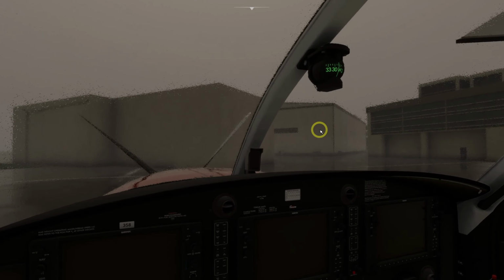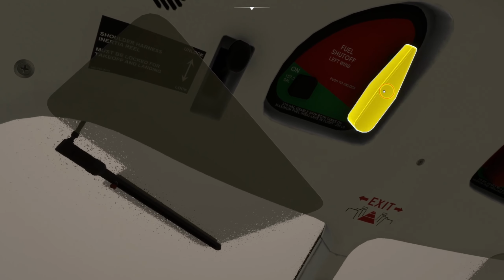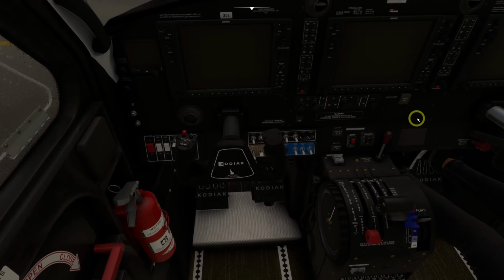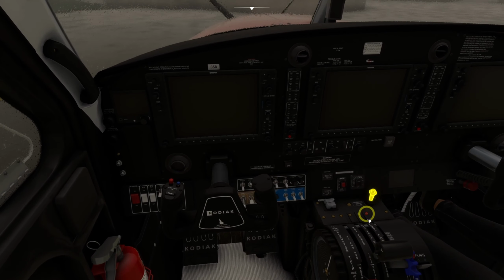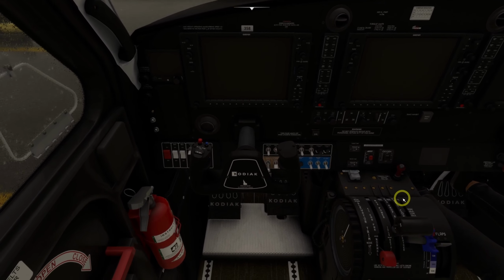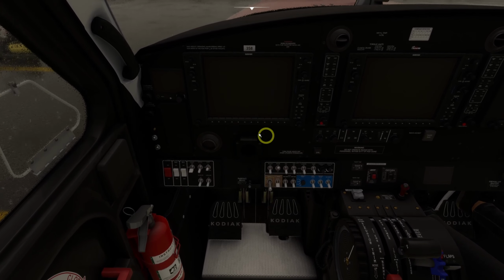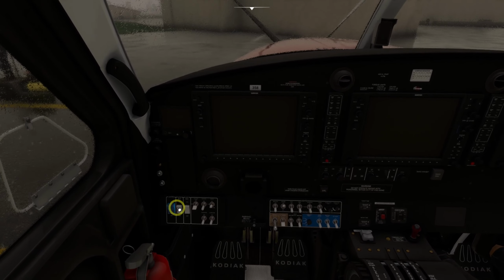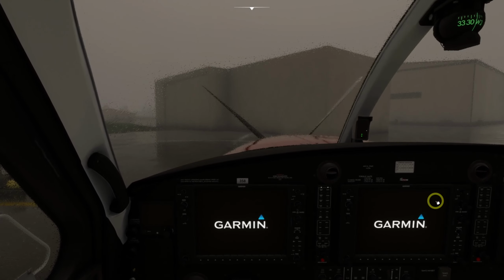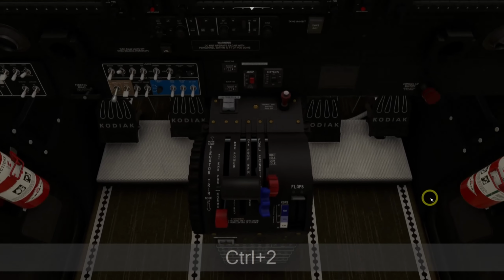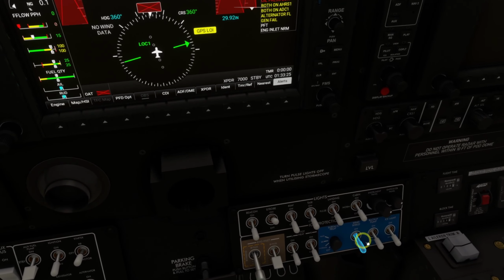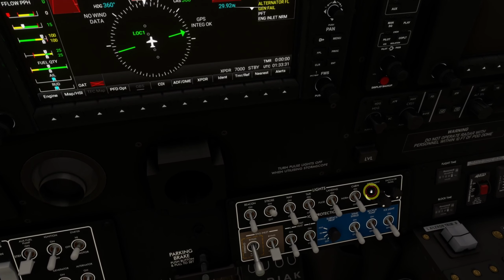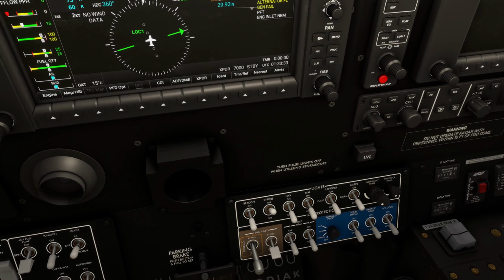And look, this is how I fly this aircraft. I'm trying to turn my fuel on to the left and the right one. The little firewall shut off, I want to push that in so I do have fuel available when I need it. I'm going to hit the pedestal to clear that. Make sure my brake is on, so in is off, out is on. And let's turn our master on. Control 2, Control 1. Look, I can probably put some lighting on this, so let's just whack some lights on. Just a little bit of lighting so we can see.